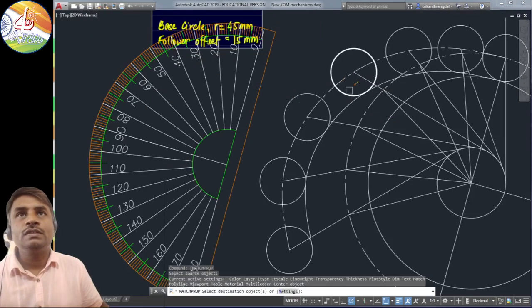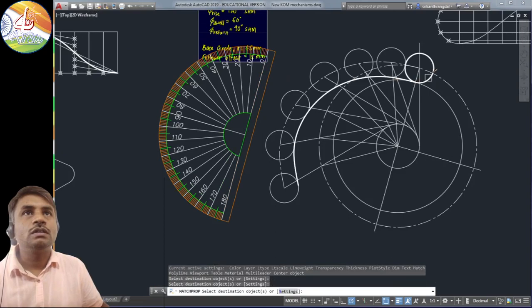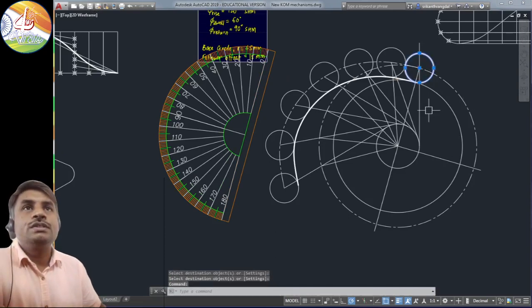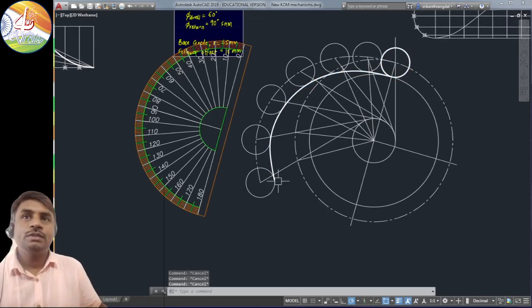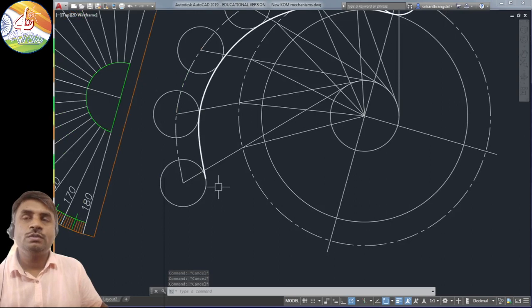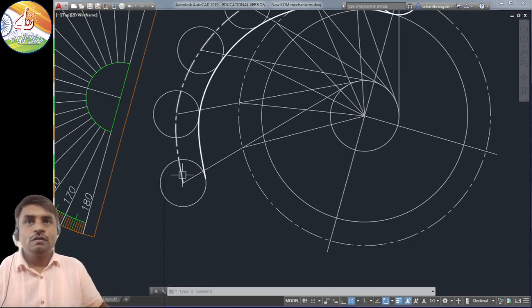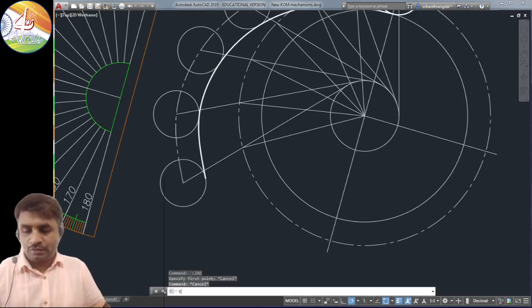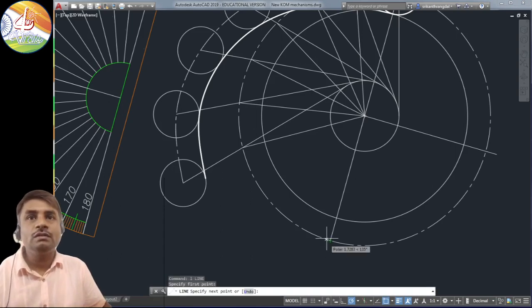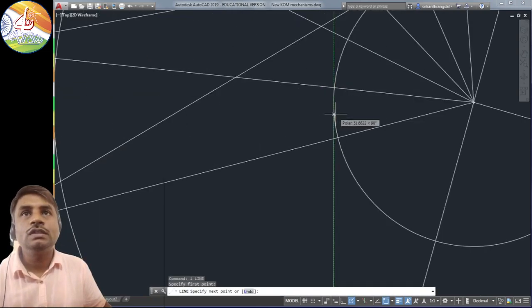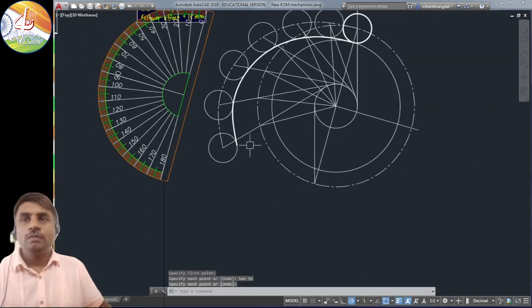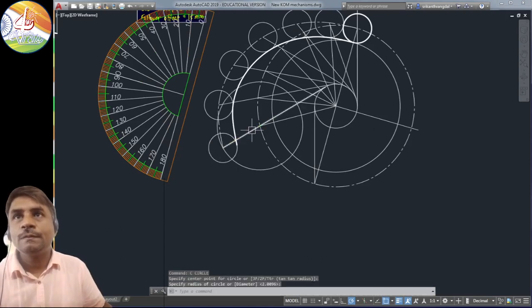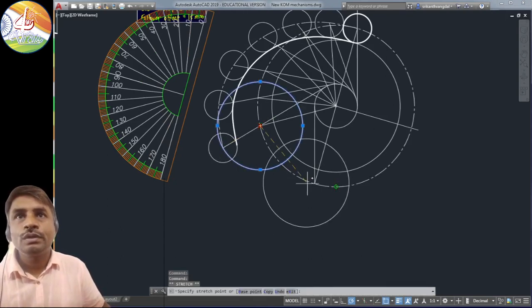So the cam profile is what we need to make dark. So this is the starting position of our roller, and this is the cam profile. Next, from here, it needs to remain at the same position for this total angle. So let us take the angle here. So this needs to be tangential. And now we need to take the same displacement that we have here to this point.